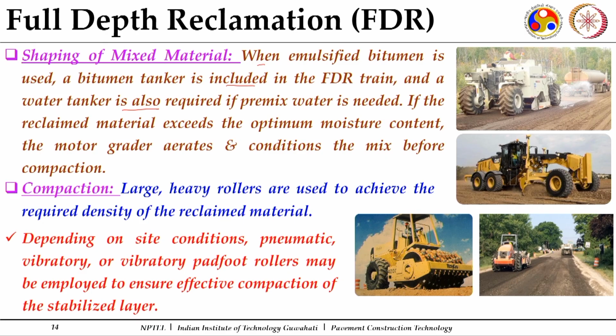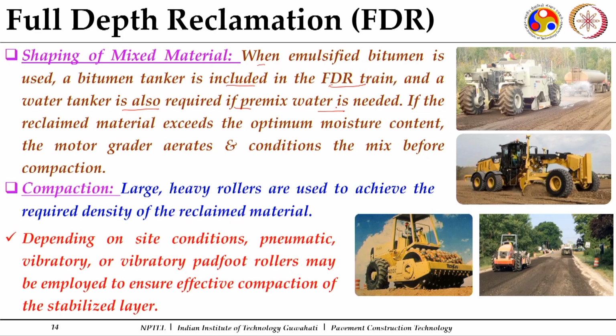So, that is taken care of during the mix design of cold recycled mixes, which we will discuss in the next lecture. In the FDR train, a bitumen tanker is there, along with a water tanker to premix. If the existing RAP already has the required amount of water content, then you do not need an additional tanker.